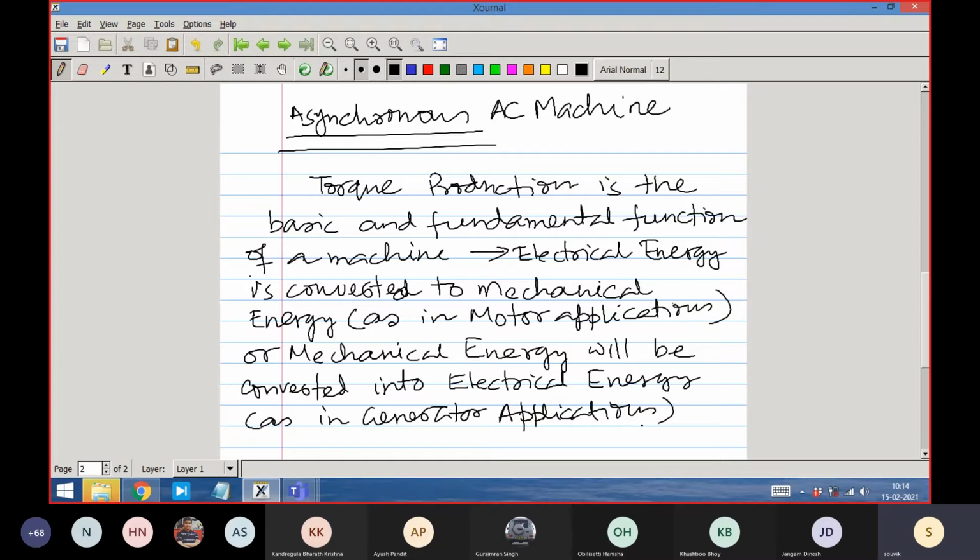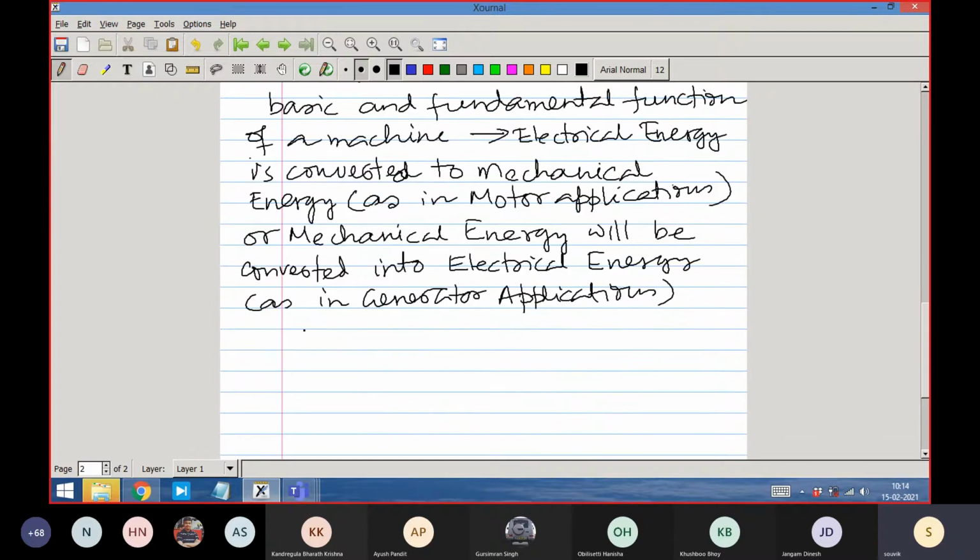So the torque expression, first philosophically, this is the torque that the machine develops. It is proportional to the flux in the air gap and the MMF of the rotor current. Only rotor current. Don't take stator current. Torque is produced in both the stator and rotor, but stator cannot move, it is frozen.